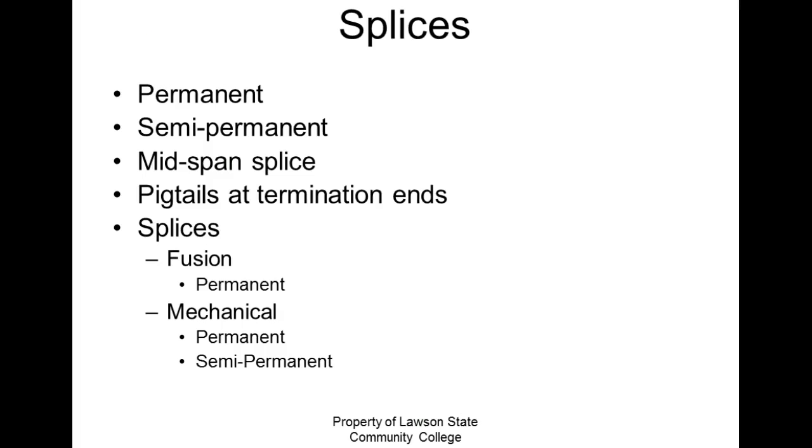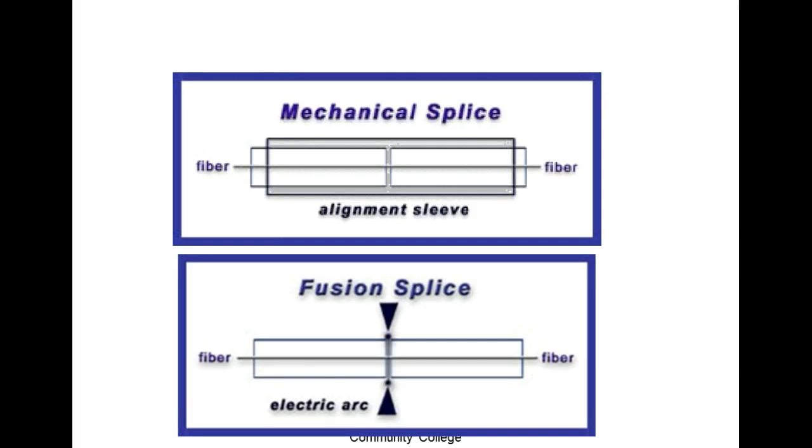So we'll let y'all see the FiberLock splices. I didn't see one in there right off the bat. These are permanent splices, and then the semi-permanent would be the ultra splice that we just passed around. So what a fusion splicer does, it usually melts everything together. Once you've got a good fusion splice, you can't even hardly see it.